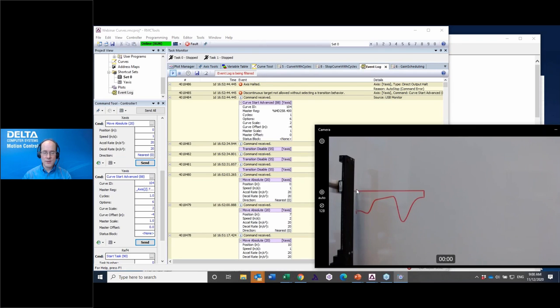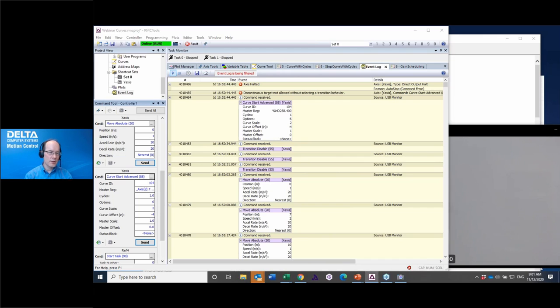So I was at 7, and I gave a command that told me I need to be immediately at 4, which is impossible, so it faults out. But what I can do is send a transition command, transition rate, that defines how I should get to where I need to be in the event that I run into this kind of situation. So max speed 10, acceleration maybe 50, and we have different transition types that define how quickly we get onto the curve.